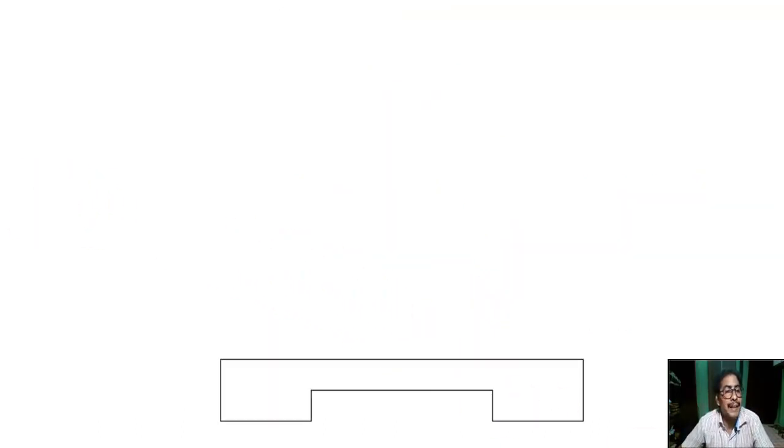Okay, now we draw a parallel line from this line, this is 90. For parallel line, click on offset command, offset distance 90, select object to offset, specify point on side to offset.